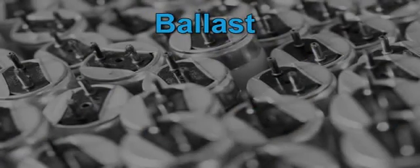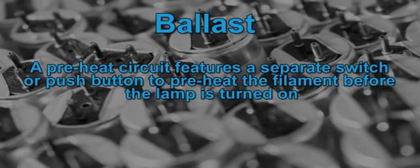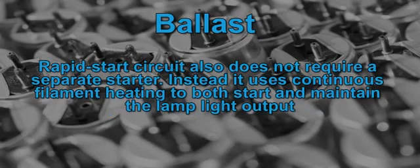Now let's look at three methods used to start the flow of current through the tube of the fluorescent lamp. They are preheat, instant start, and rapid start. A preheat circuit features a separate switch or push button. This preheats the filament before the lamp is turned on. An instant start circuit relies on a ballast that provides a voltage high enough to start the lamp without any need for preheating the filament. A rapid start circuit also does not require a separate starter. Instead, it uses a continuous filament heated to both start and maintain the lamp's light output.